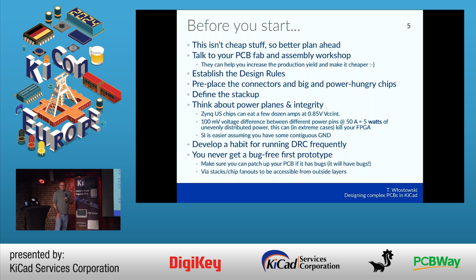Develop a habit for running the DRC. For boards of medium to high complexity, 0 DRC errors and warnings, period, before you tape it out. And be prepared to get your first prototype with bugs. They happen.